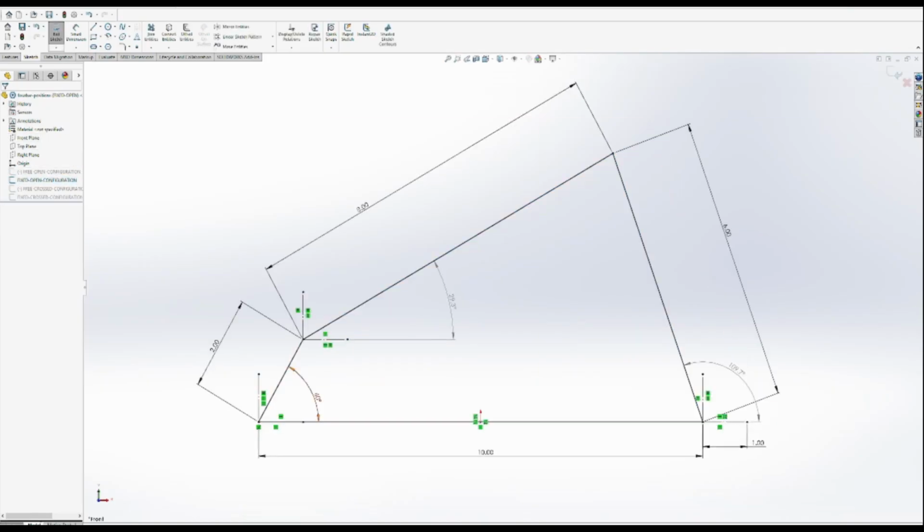So as you can see, with an input angle of 60 degrees, and A is 2 inches, B is 8 inches, C is 6 inches, and D is 10 inches, we do indeed get a coupler angle, relative to its local coordinate axes, of 29.3 degrees as predicted, and we get an output link angle relative to its local axes of 109.7 degrees, which we also predicted. So the coupler angle is 29.3 degrees and the output angle is 109.7 degrees, exactly as predicted by the position equations that we derived for this linkage for this theta 2.